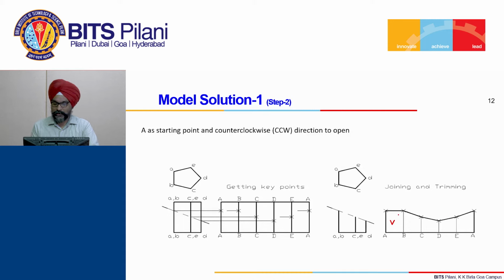It simply means that if you cut this kind of a shape on a sheet and fold it at different points like this, it will finally take this shape. That is the whole meaning. Another thing you might notice: even though it has been cut here, you have not sectioned it. The reason is we assume that it is not a solid but a hollow, or a solid composed of sheets, so inside material is not there. That is why we omit the sectioning.